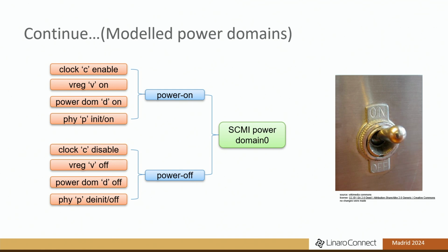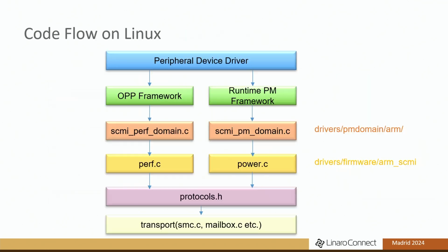And we have peripherals like camera with 20 plus clocks, so you can imagine that sending 20 clock requests to firmware just adds up. And in automotive we have very stringent requirements on the boot KPI. We have to be audio chime ready in less than 2 seconds from power on reset. So if we find an opportunity to improve the boot KPI, we go for it, even if it's in tenths of a millisecond. So that's one of the objectives also.